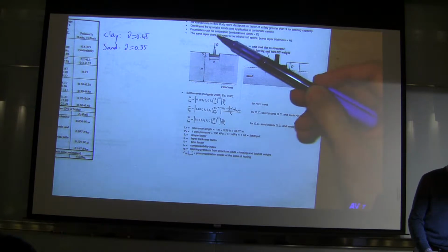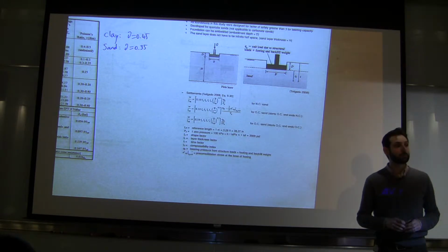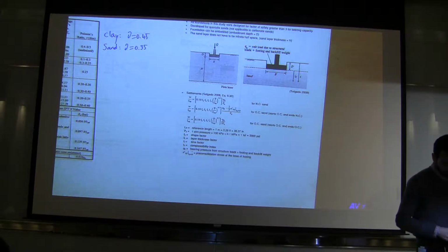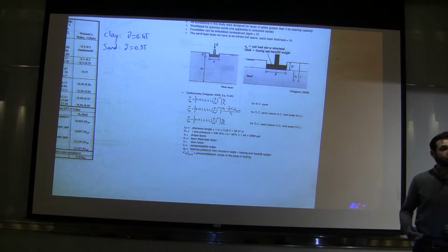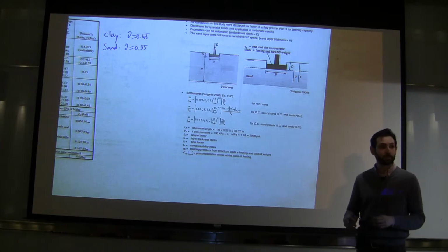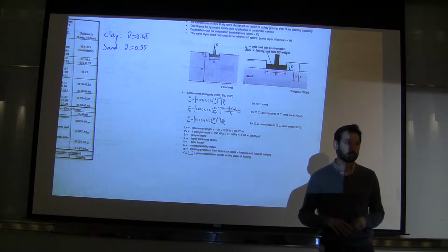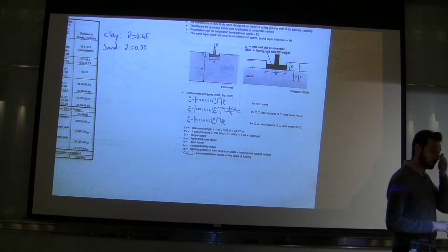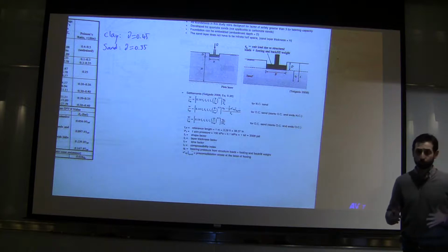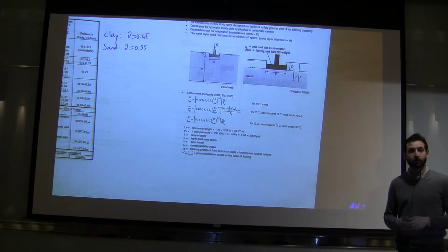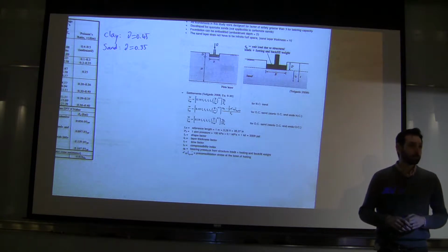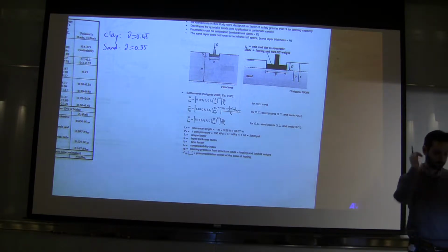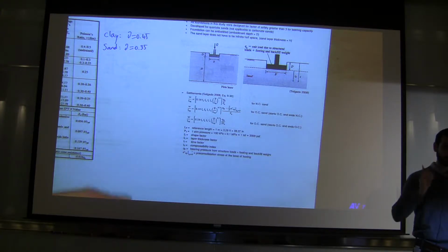They're developed for quartz sand, so you can't use it for other types of sands. But that's not too big of a limitation. Usually if you get to carbonate sands, you're in a much bigger problem. You want to do a very elaborate lab testing. And we don't really run into those issues onshore. So for building, most of the structures that you build onshore, they're quartz sands, but the carbonate sands become an issue when you go towards offshore foundations.